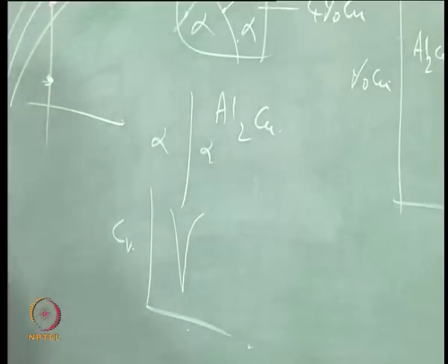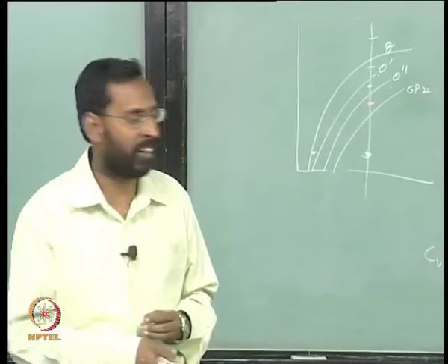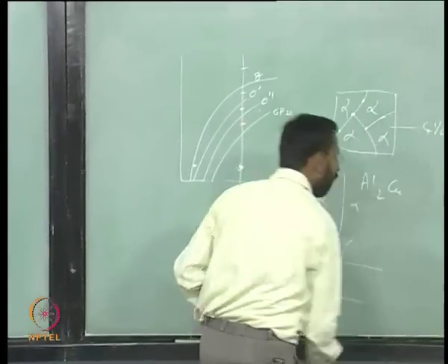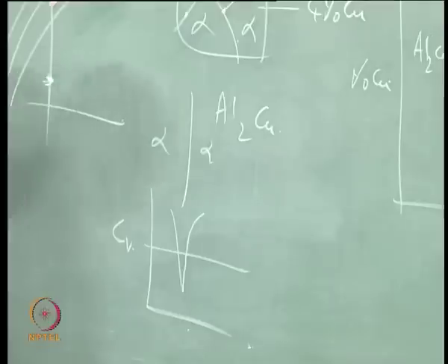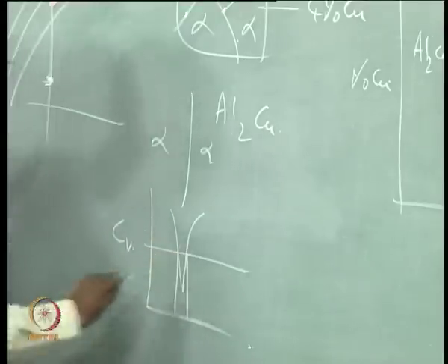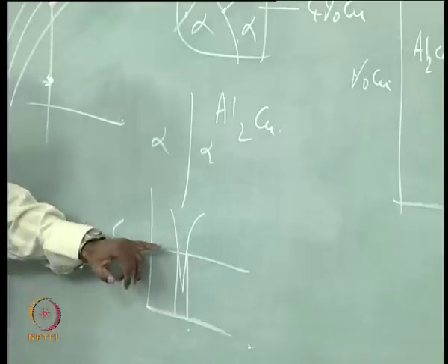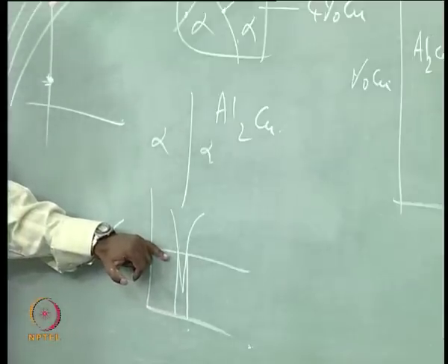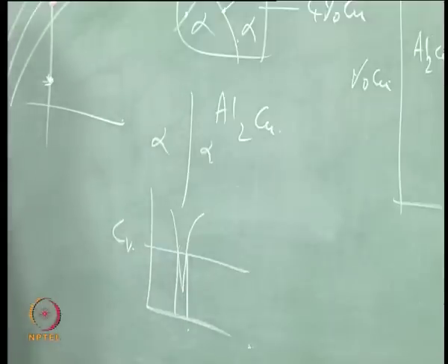And if you say that there is a critical vacancy concentration required for nucleation to take place, as you have mentioned also, you need a critical concentration of vacancies so that vacancies can act as the nucleating sites, and you put a certain value of critical concentration. Then you will see that within this domain the vacancy concentration is lower than that critical value. So, in principle, within that distance there can be no nucleation. That is the reason why we get what is called PFZ.